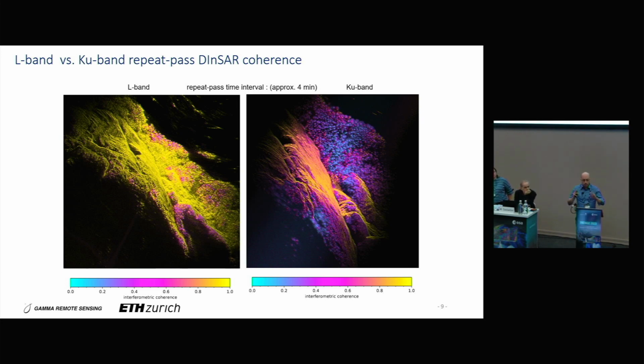So to remind you, it's not the same extent. The KU band is kind of blown up a bit compared to the L band in this view graph. So these trees here correspond to that section down here. The extent of the beam width is different, both in elevation and also in azimuth. That gives a slightly different viewpoint. So the L band system has a 40-degree beam width, so quite large, whereas this is much less in the KU band case.